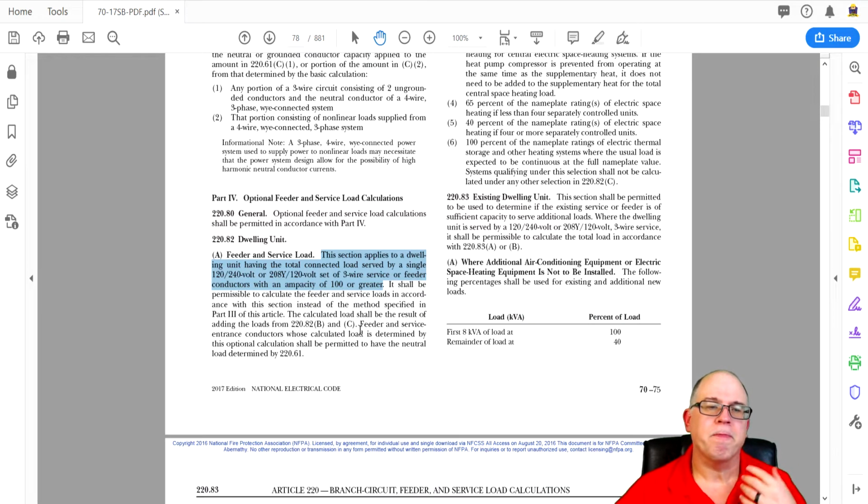All right, so in our case, 120/240 volt, and that's what we're using today. That's what ours are going to be on. But it would also apply to a 208Y/120. And in that building, you might have a 3-phase 208Y/120 where you have A, B, and C phases to ground, which is 120 volt loads. Or you might have A and B phase with a 2-pole breaker. That's a 208 single phase. Okay, and that is A, B, or C.